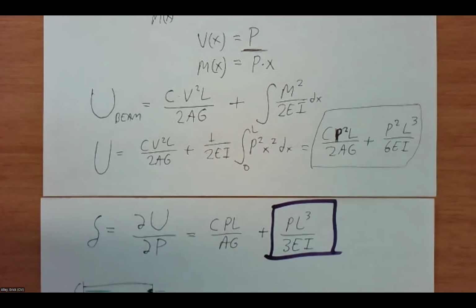But what about this? This wasn't on the slide set. Well, as we're going to turn out to see, the shear contribution for any long, slender beam is going to turn out to be pretty small if we throw some numbers in by comparison to the bending. So oftentimes people will omit this shear energy term. We do need that shear force on there because that's what makes our moment. But in terms of the energy value and the contribution to the displacement, we'll see that it actually is fairly small. All right. Anybody have any questions about how we came up with that one?